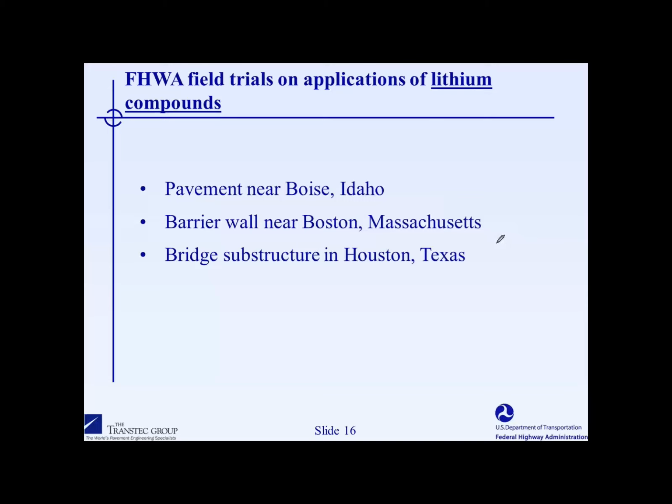And again, the motivation behind this was based on lab work that was done in the 80s that showed that small laboratory specimens, when dried out and then soaked in lithium nitrate, could reduce future expansion compared to control specimens. So we do know that lithium can affect the nature of the gel and render it non-expansive or considerably reduce the expansion.